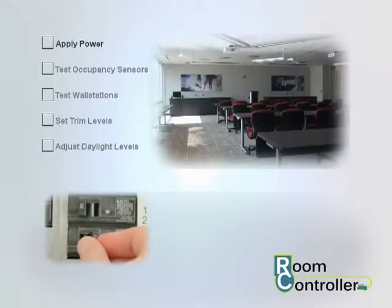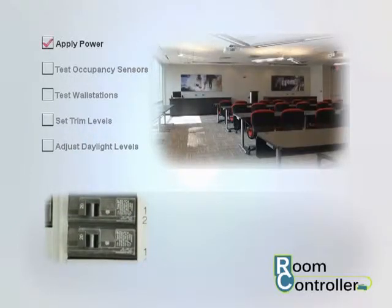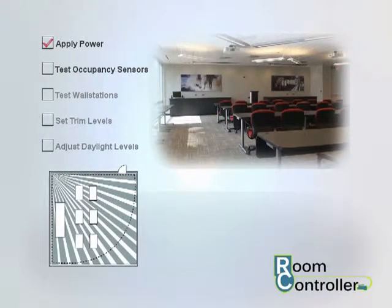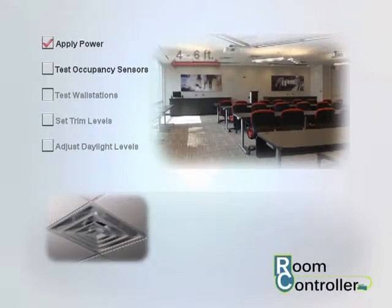Apply power to the room controller and verify that the lighting loads turn on full bright for 3 seconds before they begin normal operation. For room controllers connected to occupancy sensors, verify that the sensor has been properly located and is at least 4 to 6 feet from any air supply ducts.